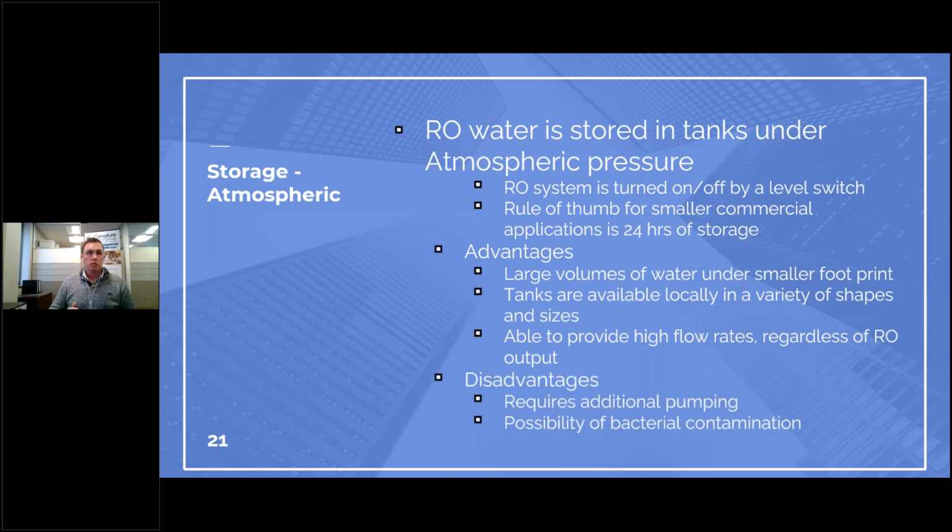Disadvantages on this side too is that you actually need additional equipment for pumping. So this adds additional floor space, cost, and that sort of thing. And then depending on your storage tank, you've got the possibility of bacterial contamination. You can get around that by adding what's called a hydrophobic vent, but that still may not be enough depending on your area and the regulations required.